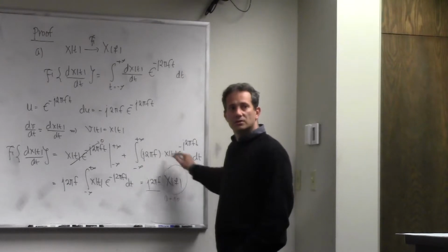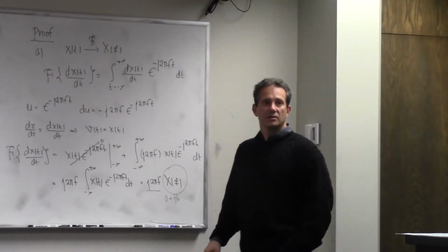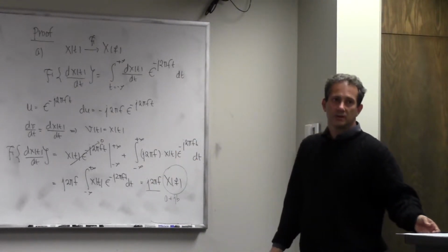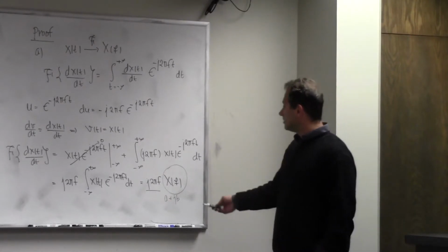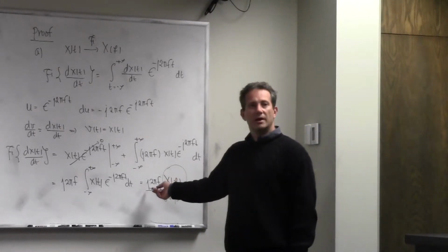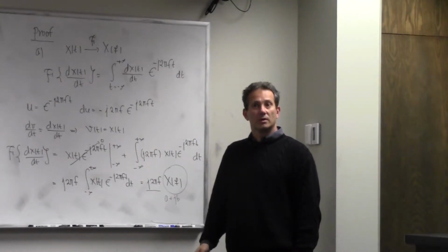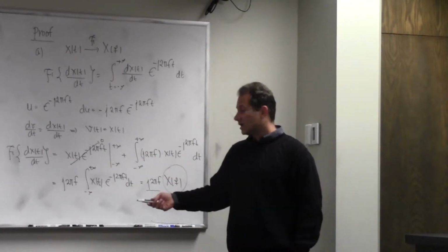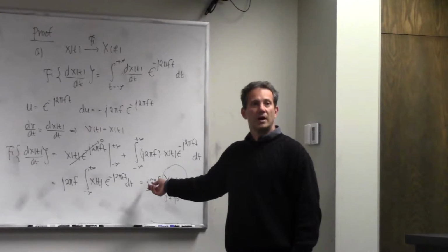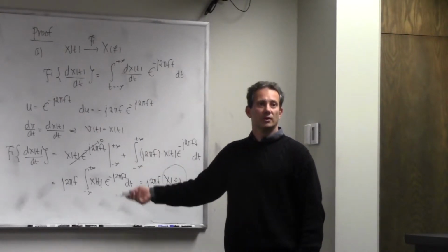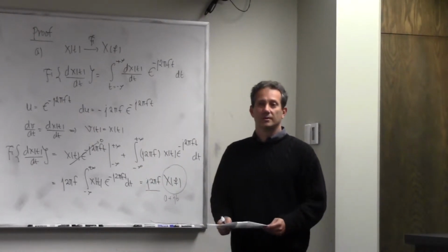So this whole thing has a real and imaginary part altogether. It is multiplying the magnitude by 2 pi f, which means that the higher frequencies are multiplied more, their magnitude increases, and it's introducing a phase shift of pi over 2 to each sinusoid. Right? That's what it's doing.